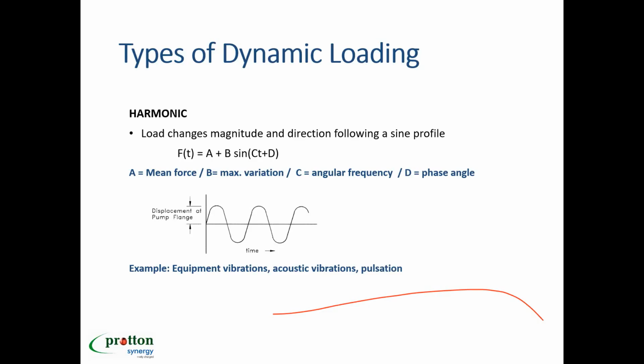Even flow induced vibrations, if you know the pattern of the flow, what is happening, it can be done as a harmonic analysis. And sometimes one kind of analysis can be done as a harmonic and as good as a random.